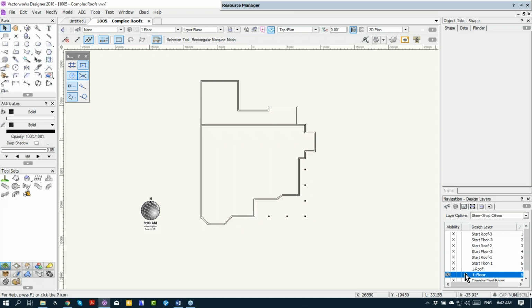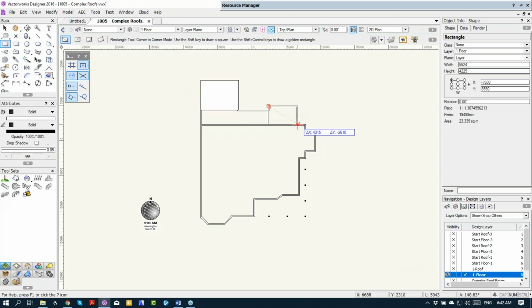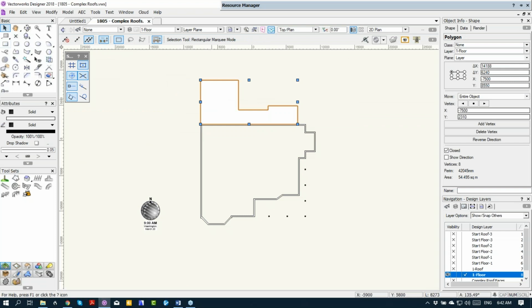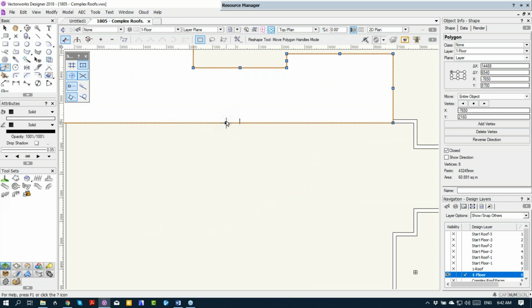I'm going to hide the roof there. Quick way to make it, I can't use connected walls because it just won't work that way, because those don't connect enough. And I'm just going to draw over with my rectangle tool, add those together. So here, what are we going to do? Well, this has got a slight overhang maybe, so we need to offset that a little bit, probably only 6 inches. But when I do that, don't forget, I've also offset the front edge here. So we might need to pull that back to there.